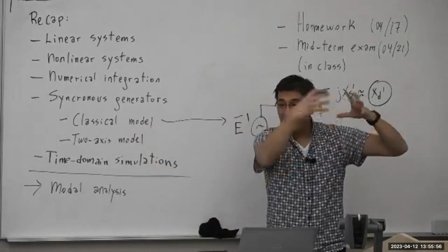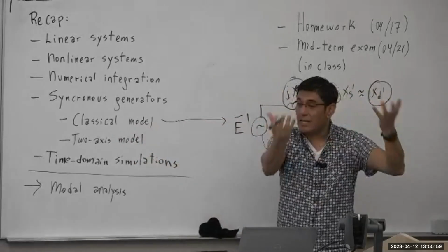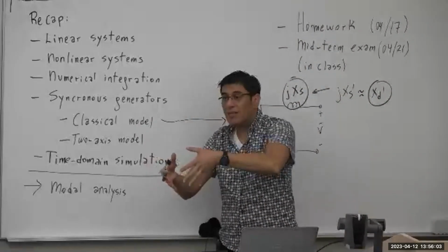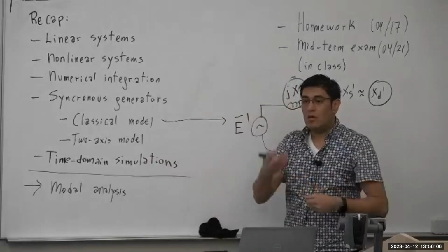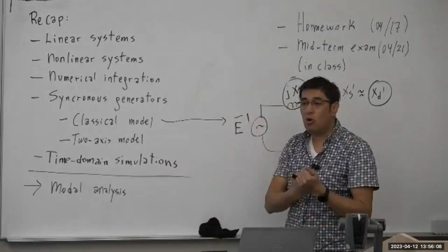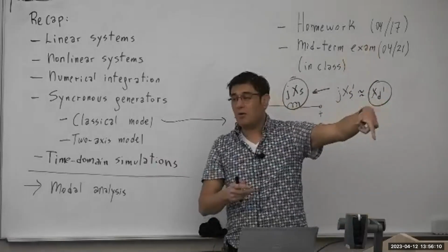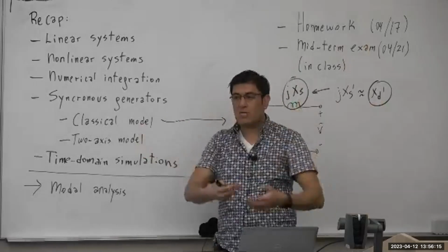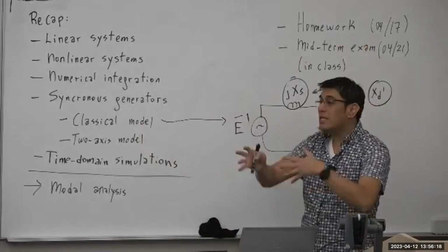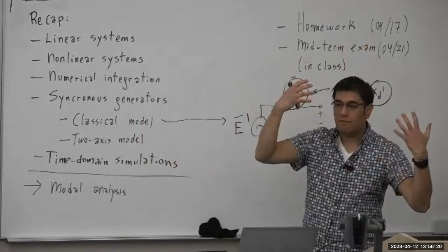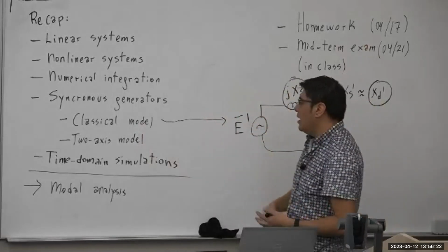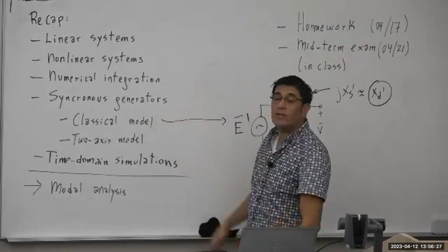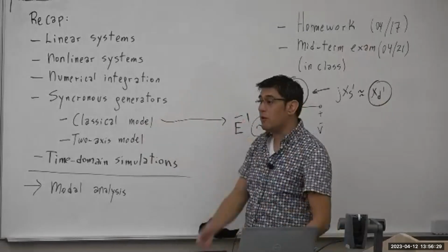So what we did, all these currents in the stator that are changing sinusoidally, when they are equivalently expressed at the rotor, they're stationary with the rotor. So that's why we got a D and Q component for the current from the stator. Now, IA, IB, and IC are expressed in terms of ID and IQ. The same thing for voltage, and the same thing for flux at the three phases. So we introduced that definition of DQ component, and we proposed a two-axis model that we have used already in our example.